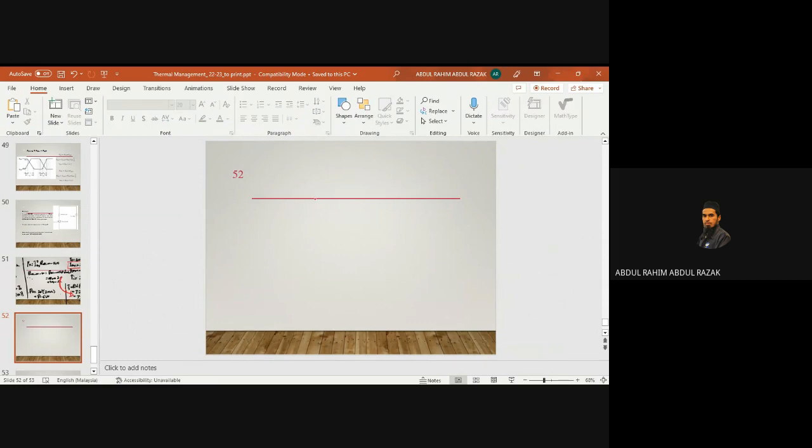Okay, how much maximum current without heatsink? So still without heatsink, maximum ampere sama dengan berapa? So same formula you have to write, which is Tj equal to PD R thermal, because we have not yet used any heatsink, R thermal Ja plus TA. Same scenario just now. Ambient is 40 degrees C. This one is decided by your designer, your boss. You said you want to set your ambient at 40, so you just put 40. So without heatsink, and so we have set our Tj at 120 degrees C.